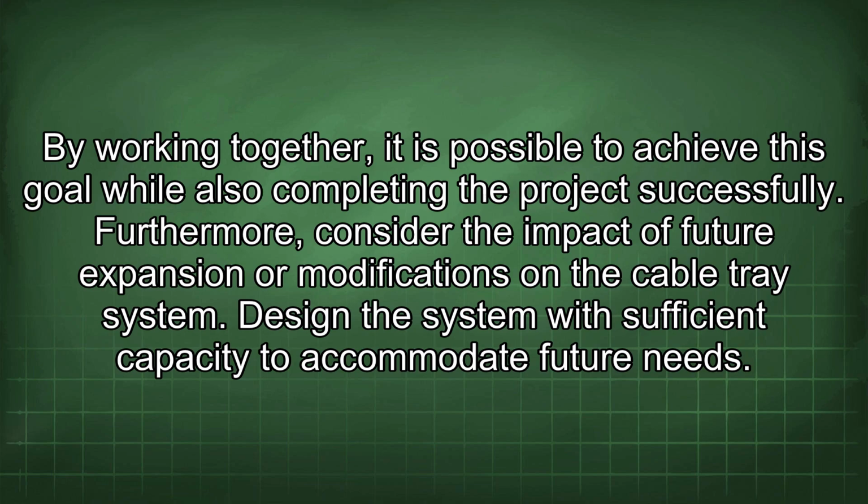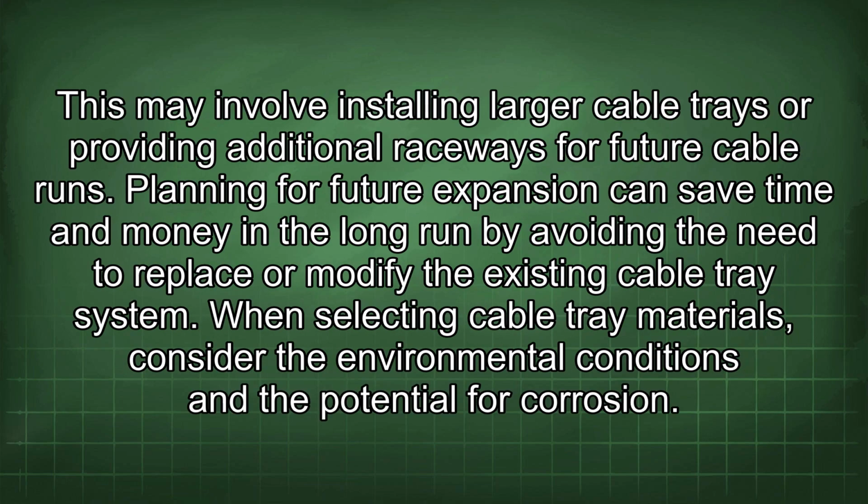Furthermore, consider the impact of future expansion or modifications on the cable tray system. Design the system with sufficient capacity to accommodate future needs. This may involve installing larger cable trays or providing additional raceways for future cable runs. Planning for future expansion can save time and money in the long run by avoiding the need to replace or modify the existing cable tray system.